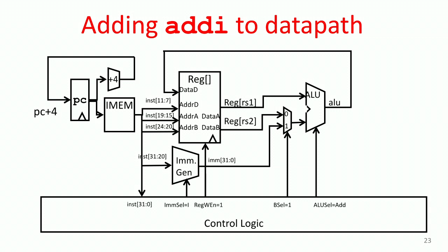So something will come out here. It's important to remember the way hardware works. This field in this instruction will hold something that is interpreted as a 5-bit register specifier. And so something will come out of the register file, but it will be ignored because it's going to the input of the multiplexer that is not being selected. So it's kind of wasted effort in some sense. We're driving those lines and switching those signals, but then we're going to ignore it. This is one way that power gets wasted in these circuits, because we do a lot of things in parallel and just select what we want, because we want it to go fast.